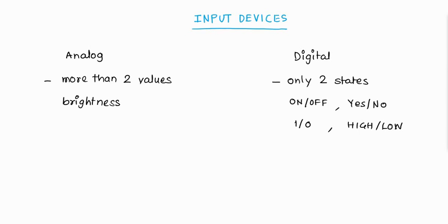Now, when we are talking about output devices, the maximum output value we could give was 255. That was the maximum output value because our microprocessor is an 8-bit processor, and hence the maximum value we could give is 255 because we can only give total 256 values, and the range of values we can give was from 0 to 255.